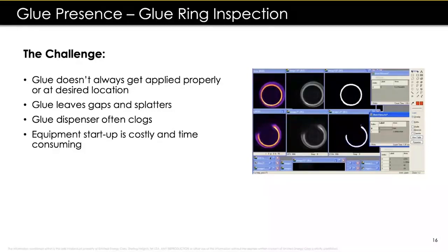So if we have, let's say, 200 pixels that we need to see in this temperature range, we validate that there is enough glue or adhesive in that particular region or specific area of interest. If we're short of that density mapping, then we know we have a weak bond, or we're going to have a weak bond, I should say, once we marry the products, and that will cause the leakage.